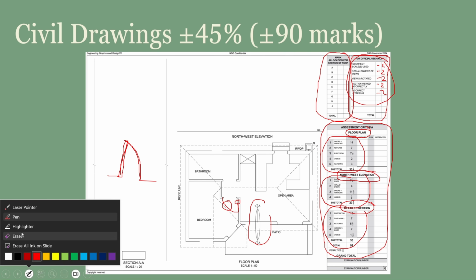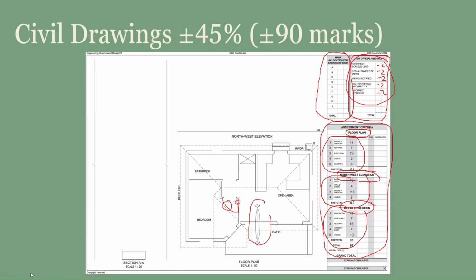Then when it comes to the windows, windows usually have a window sill. So you will have a window, and then the frame of the window should be in the middle of the wall. So just take note of that. Be careful, because the opening that they give you, from there to there, is usually bigger than the actual window that you need to draw in.